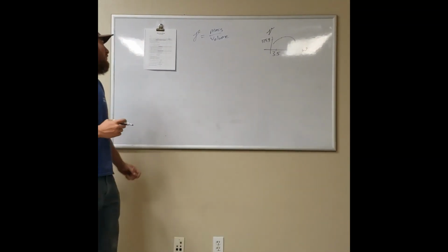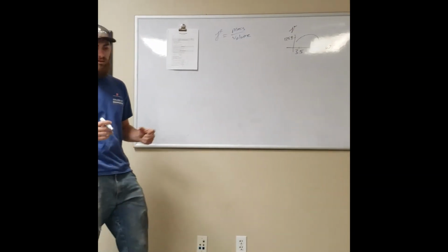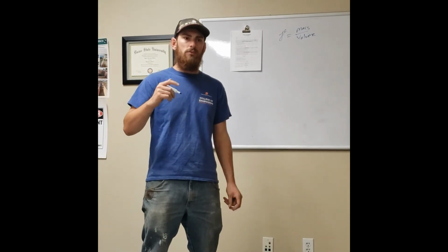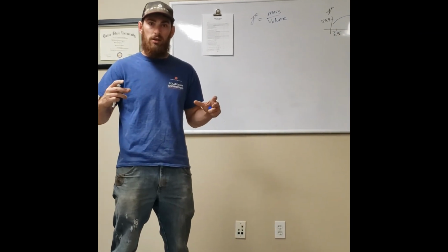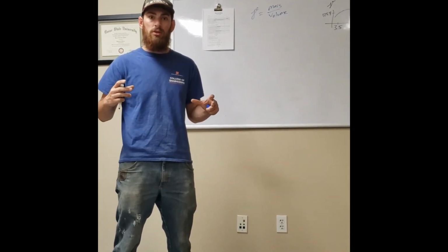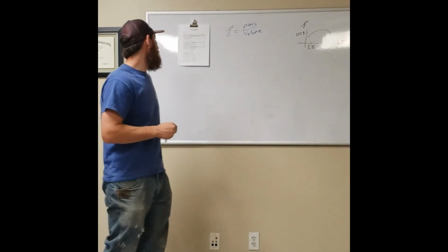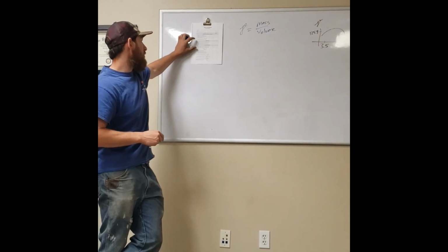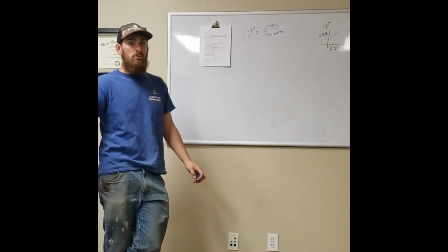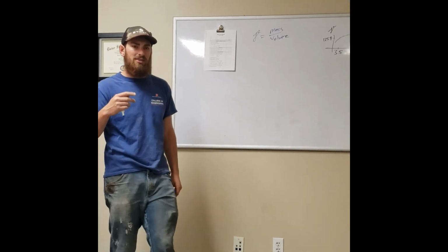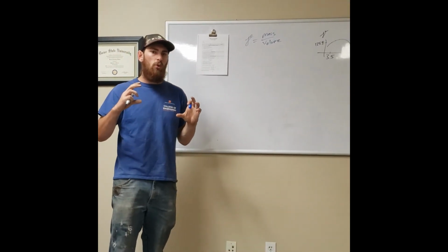Next thing that we're going to need to do is calibrate the cone itself. The cone, like it sounds, has a cone on the base and a big jug on top. So I'm going to set it up on a flat piece of ground and let the sand run out into the cone, and that's going to give me a couple different weights. So it's my before weight of running into the cone and my after weight of running into the cone, and with that we can calculate exactly how much extra sand is going to be on top of the hole.